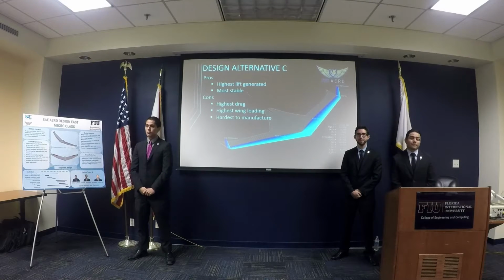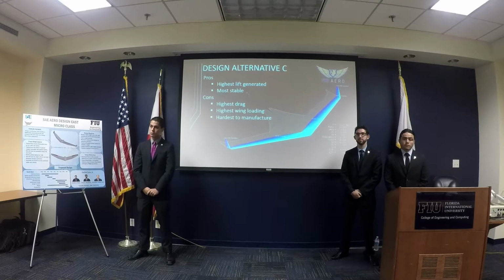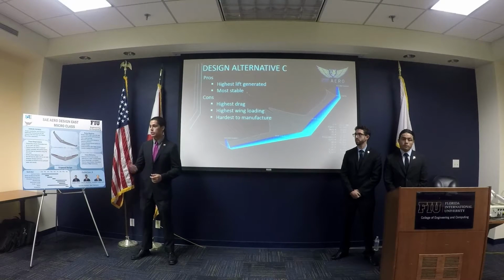When you go into that modular design, now you've got to consider your loads on those specific pins that you're attaching, because you're no longer distributing that load over your airfoil section. It's now being transferred through whatever joint you're putting on that. And during a bank, we might experience 3Gs or 4Gs times the 4. So quick off the bat, 6 times 3 will be probably 18 pounds on those joints. Divided by 2 wings, maybe 9 on a good day. Add some factor of safety. Yeah, we're looking at about 15 or 14 pounds off the top of my head.